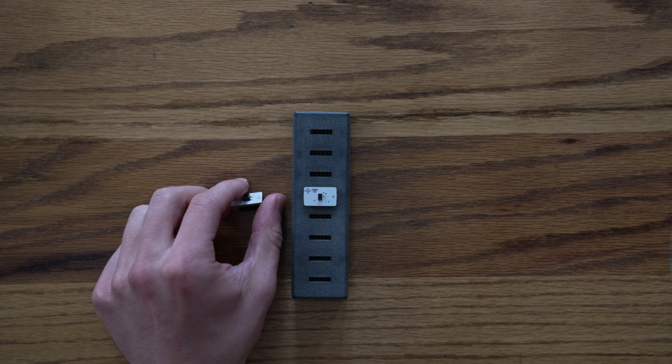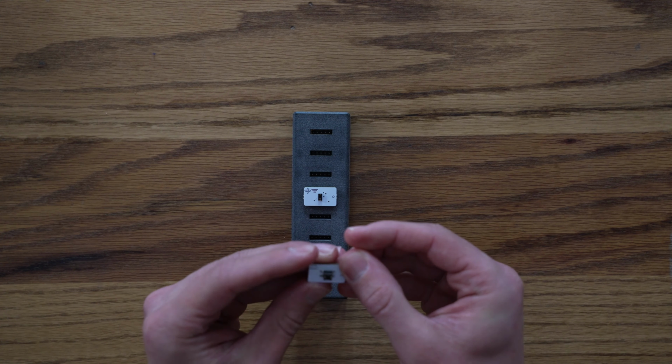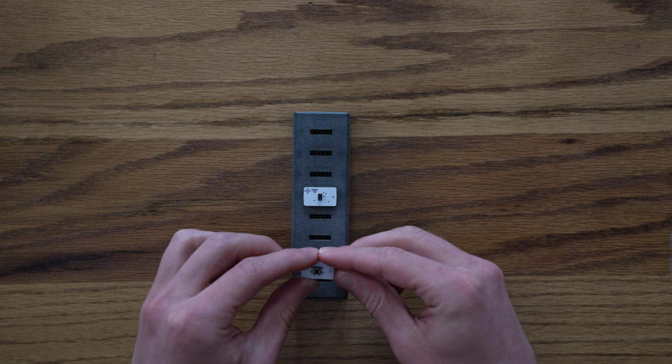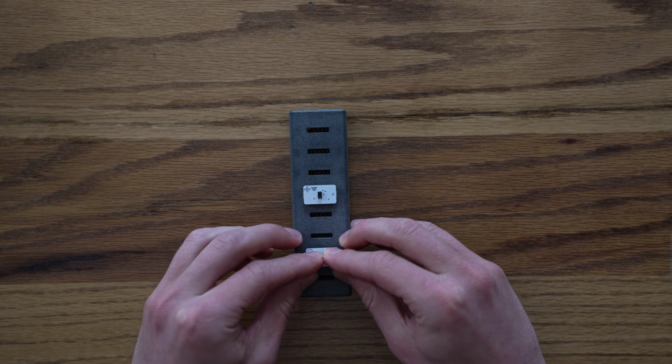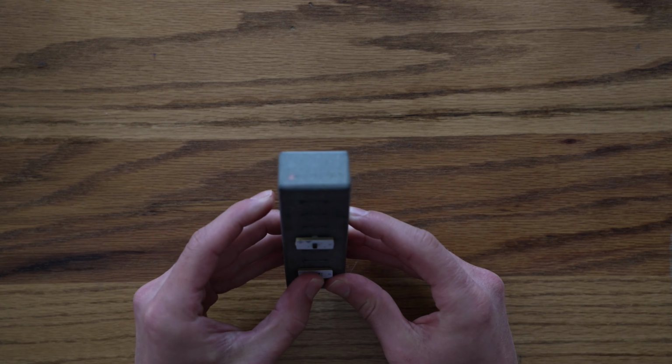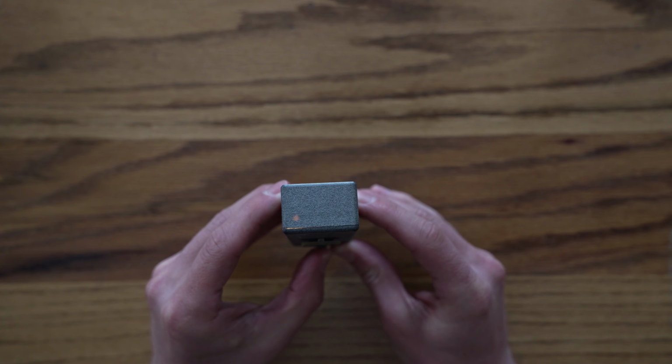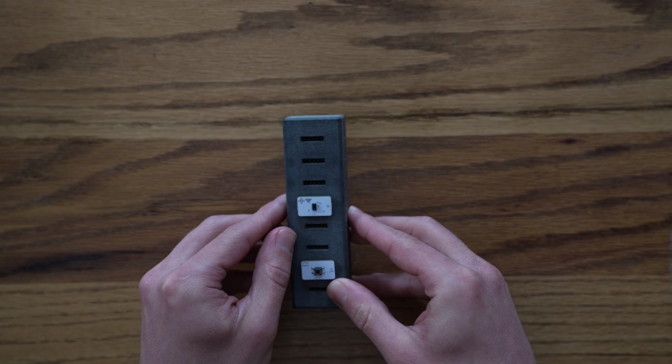When you're done with your music remote and ready to exit keyboard mode, plug a button module into port 7 and hold it down for 5 seconds. You'll notice the status light turn back to white, and the device will start to appear in scans. You then must also go into your Bluetooth settings and forget the device so that you can pair it with the app.